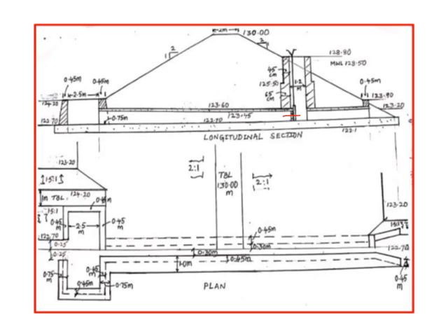So we have to see the ground level at the site, which is 123.2. So this is how you, this is the plan at the bottom, plan at the top, whereas the long section has been drawn according to the RLs that we already learned in our irrigation design class. So it should be easy, and I have already explained to you how to draw this tank sluice part,